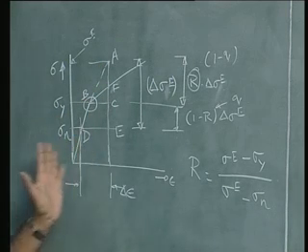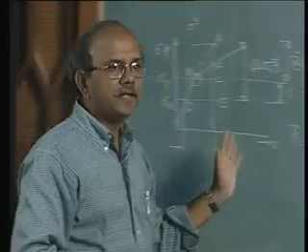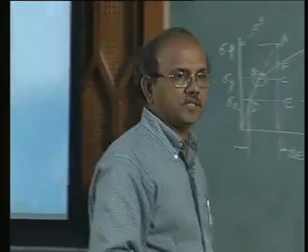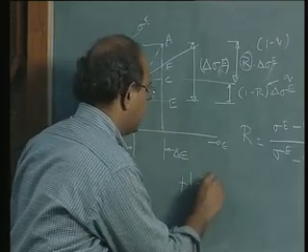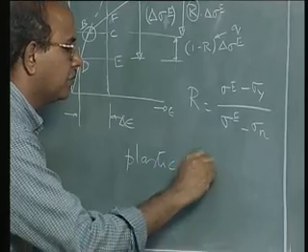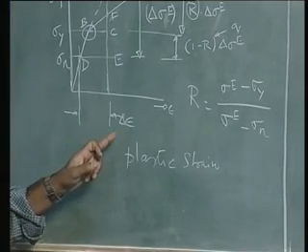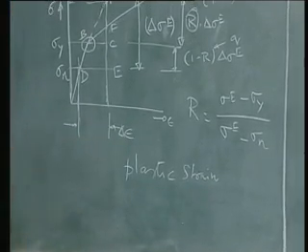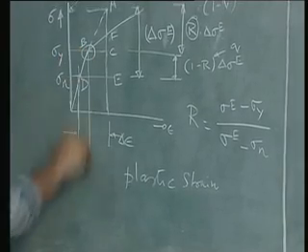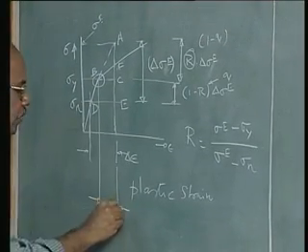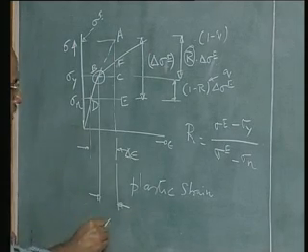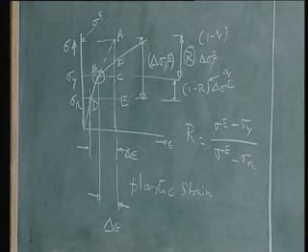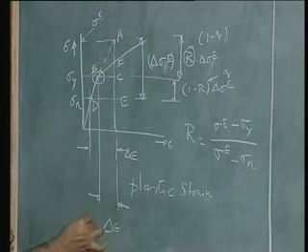Now, having understood how we write down the updated stress, there is a very important quantity which requires attention. What is that quantity? That quantity is the plastic strains. What I have essentially done is to look at the total strain, and from there we can also separate out the elastoplastic strain, maybe we call this delta epsilon EP.